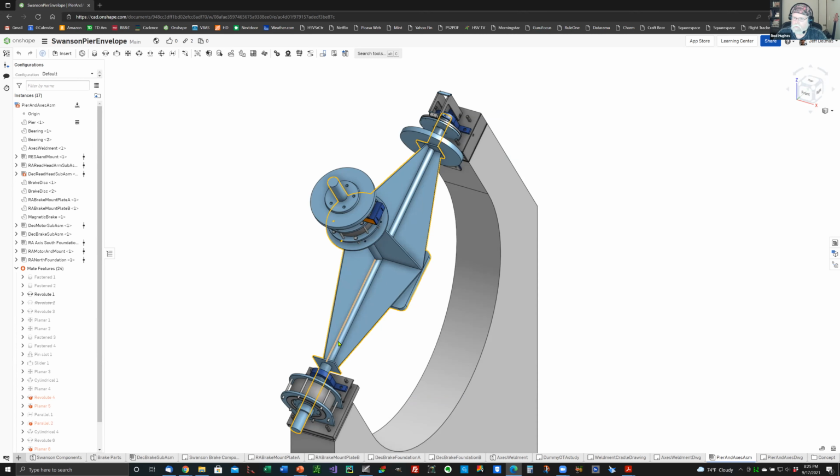It's just that the motors lose all torque instantly when you power off. So if there's any imbalance in the telescope, it would just flop around. And since there's no gear system, there's no mechanical disadvantage that acts as a brake. In that case, it's whatever friction is in the bearing is all you've got at that point.